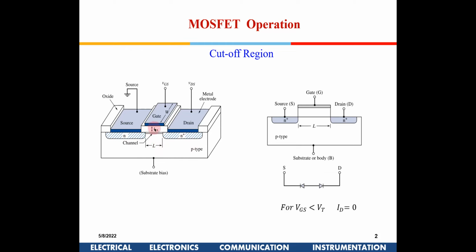Then you have an insulator, which was generally silicon dioxide in the earlier days, but as the technology has advanced and the device sizes have shrunk, the oxide thickness also needs to be accordingly reduced. So for very low technologies like 45 nanometer and all, the oxide thickness becomes very thin, so it becomes unreliable and can get punctured, right? So instead of using silicon dioxide, these days we use hafnium dioxide or a high K dielectric, which has got the same electrical characteristics. It has got high K.